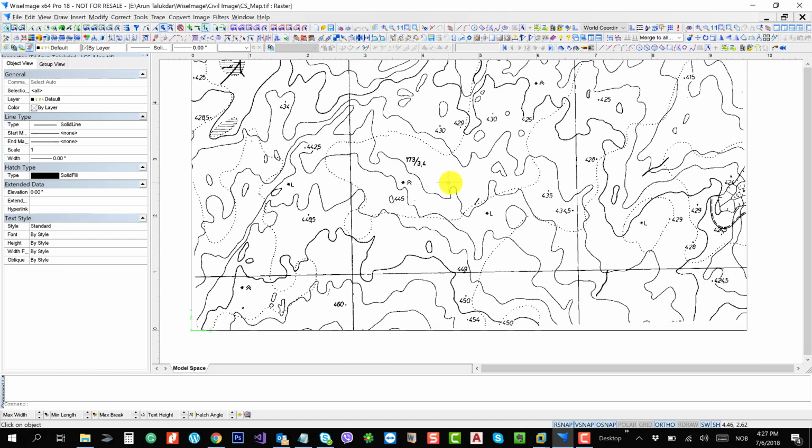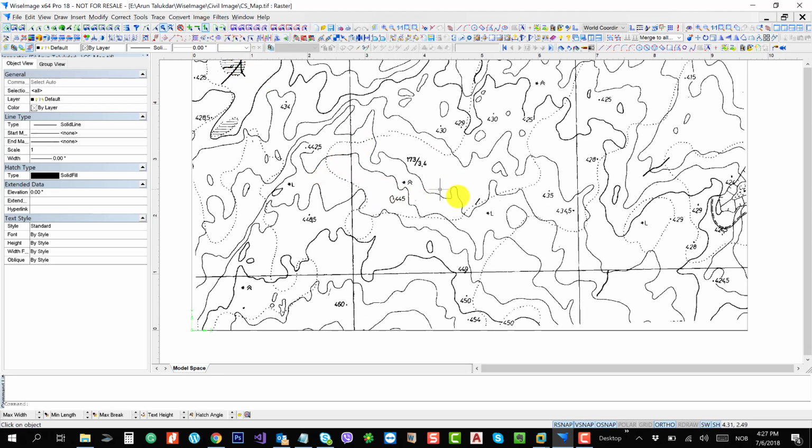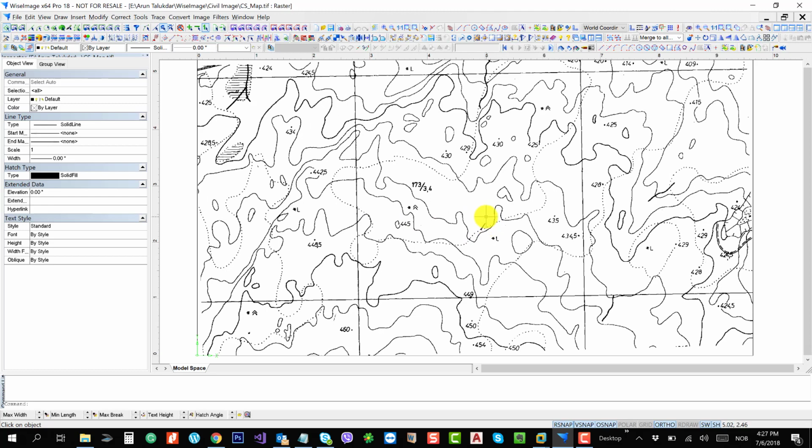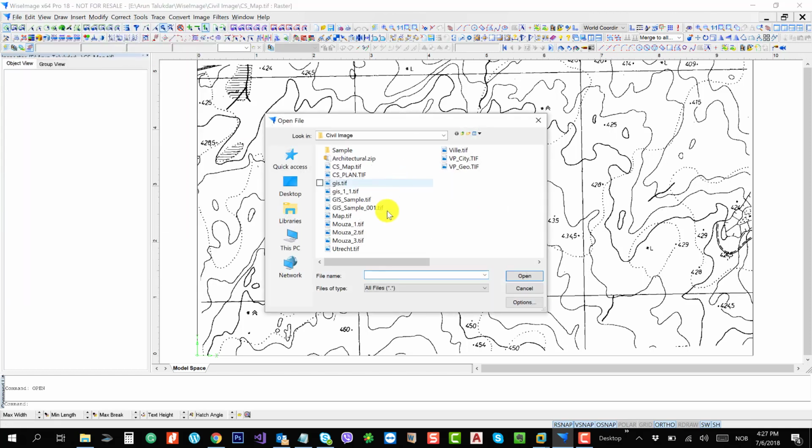Maybe, yeah, this is a good example. So let's move further down to convert raster images into vectors. If you're not satisfied with all of the quality enhancements, editing, and hybrid editing, you have options to actually convert things into vectors. Not for all the files. If you have a complicated maintenance drawing, it's always recommended you go only for raster editing, creating hybrid files, not for